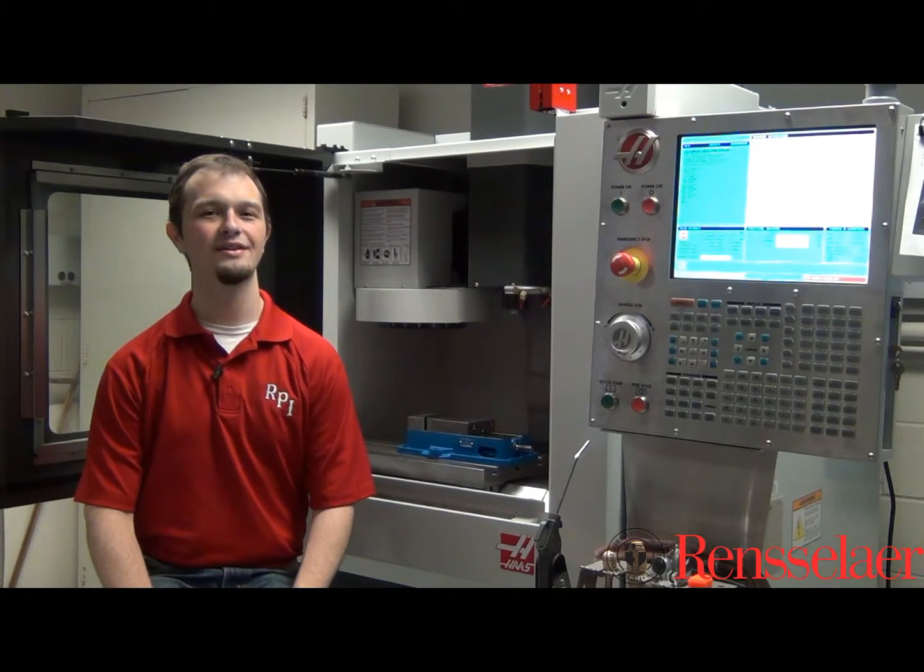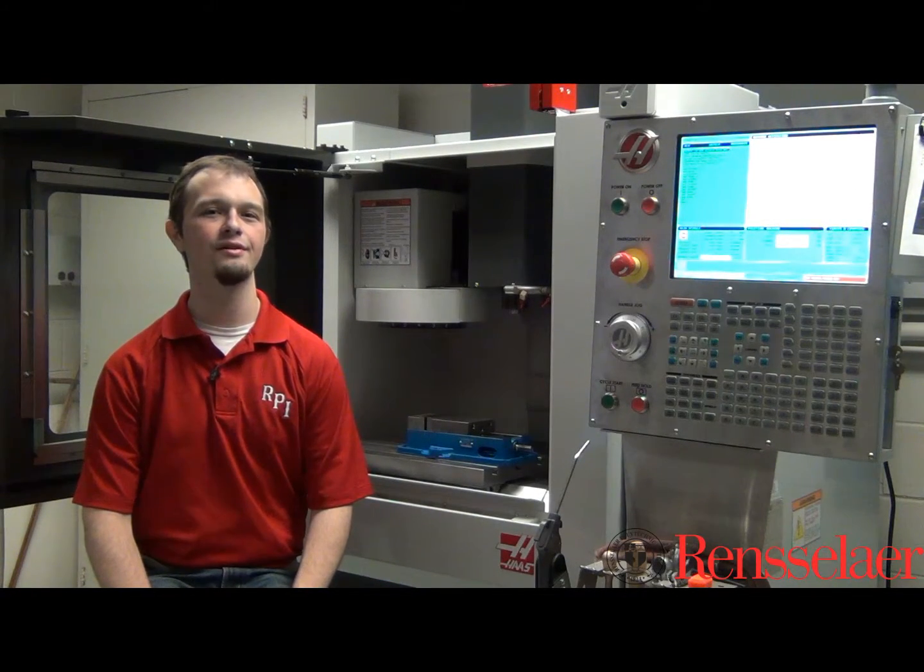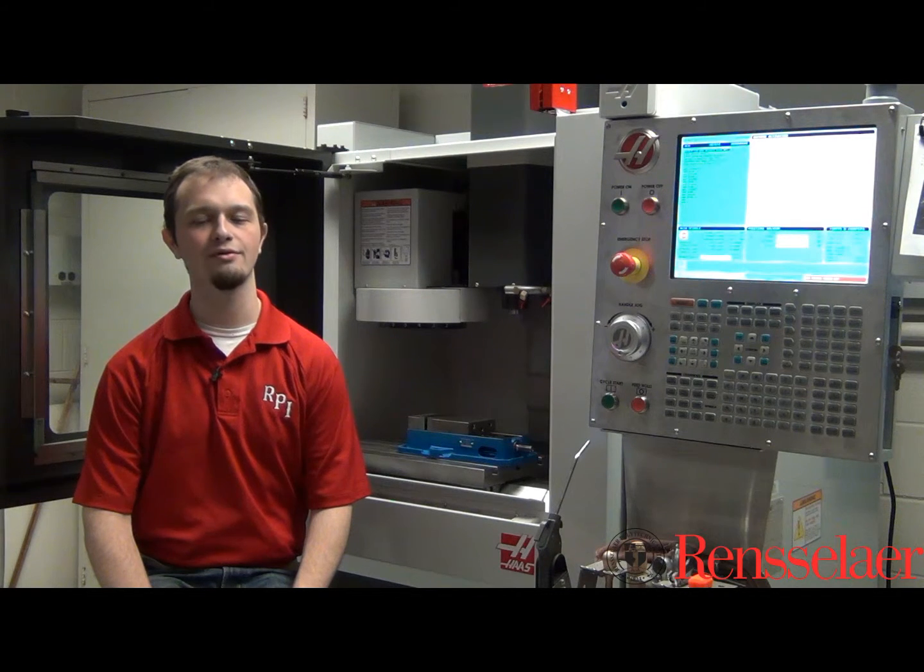As we look into more detail at the table feed rate, we see that it's the product of the chip load, the number of cutting edges on our tool, and the spindle speed that we calculated on the previous slide. Therefore, at the micro scale, because our spindle speed is much higher, our table feed rates are also much larger than their macro-scale counterpart. To help aid you with these calculations, please see the cutting speed calculator spreadsheet located in the module. One thing to note, however, is that this cutting speed calculator will output values in SI units, whereas most machines in America use traditional English units for the coordinates and table speeds.